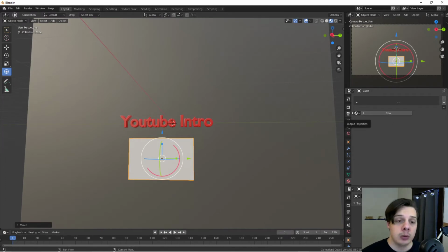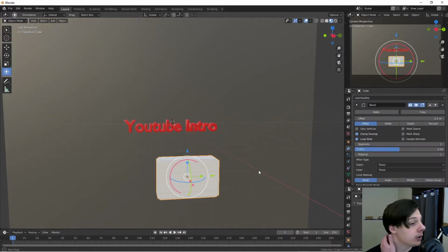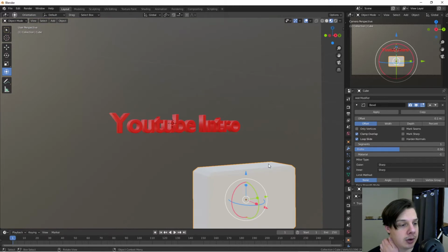So now we are going to add in a modifier to create some bevels. So click the modifier button. That button is the blue wrench button on this panel. Click Add Modifier and then click Bevel. So it doesn't look very good right now. So what you want to do is give it 32 segments. So where it says segments, type in 32.